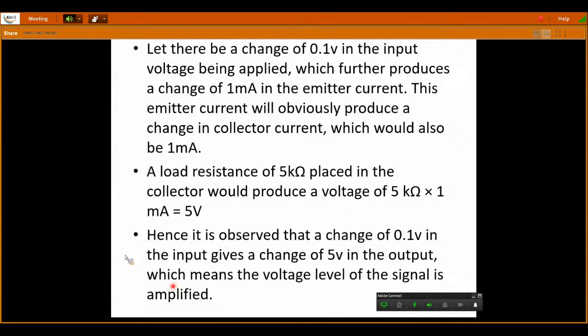So your circuit is a common base amplifier, and in a common base amplifier the current gain is 1. Hence the output collector current IC is also approximately 1 milliamp.